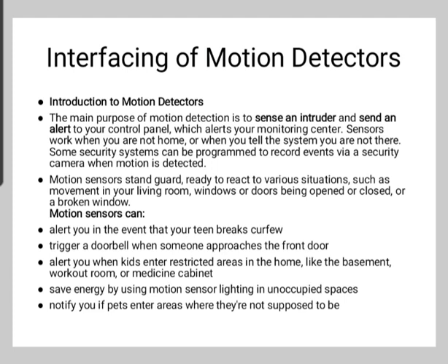amplifier. Whenever a stationary object is in front of the sensor, the two slots receive the same amount of radiation and the output is 0. Whenever a moving object is in front of the sensor, one of the slots receives more radiation than the other slot, and this makes the output swing high or low. This change in the output voltage is the result of detection of motion.